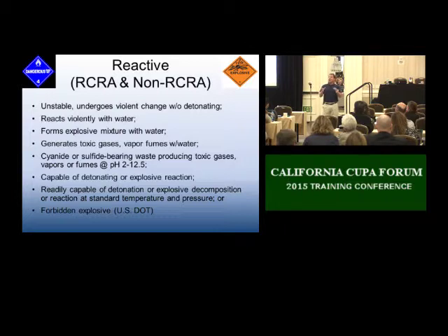That's a waste. Now that's coming from the dry cleaning operation, and it's a chlorinated solvent, PCE, and that chemical is listed as F004, F005. It says that if you use this chemical in a process greater than 10% concentration prior to use, and you produce a waste derived from using PCE, a chlorinated solvent, and you collect the waste, that is an F-listed waste stream because I use that solvent. No longer is it U because you've used it. It's a spent process, and that chemical is identified in the F codes. So all of a sudden, the same material that I get rid of after use has an F listing associated with it, which makes it a federal RCRA waste.